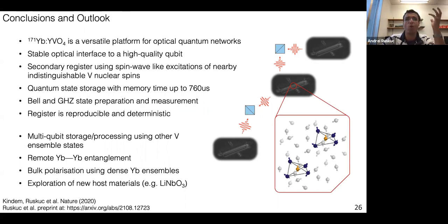So for instance, one additional potential downside to the current platform is that ytterbium emits at 980 nanometers, which isn't within this low loss transmission region of optical fibers. So if you could use lithium niobate and then perhaps even use the nonlinearities to do up conversion to 1550 nanometers in the same device, or even in the same photonic platform, I think that would be a very powerful demonstration. That's maybe a motivation for lithium niobate specifically.